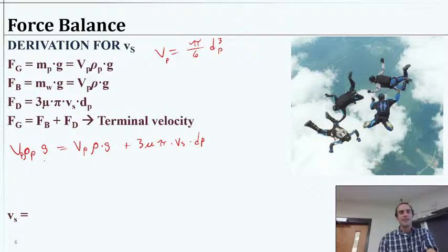Thank you. Okay, so with this, we really want to solve for the velocity term, because that's what we're interested in. We need to know how fast these particles are settling. That's going to tell us how we can design our system to settle them in time before the water leaves the sedimentation chamber. So I'm going to subtract this buoyancy term from both sides.